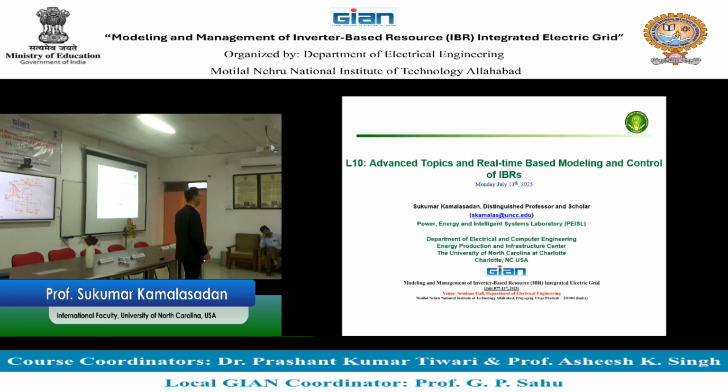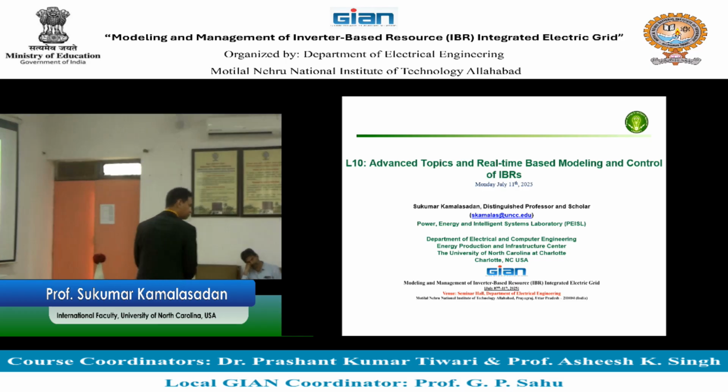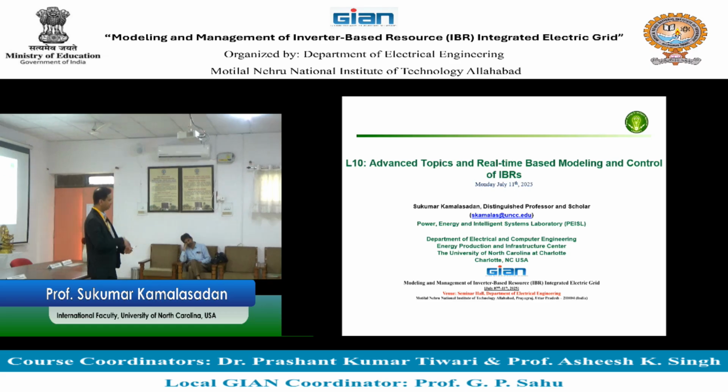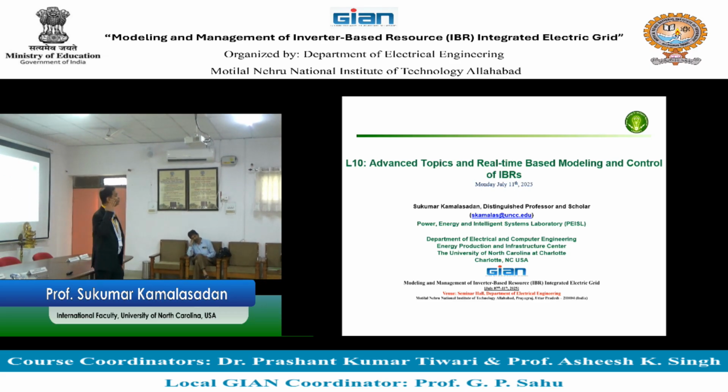So this is done by extracting the angle from the frequency through a method called PLL. Not worried about voltage magnitude. Why? Because the grid is there and the grid is connected, so the voltage magnitude is there, right? You need to control the voltage magnitude, but you are not worried about developing the voltage because it is already there.